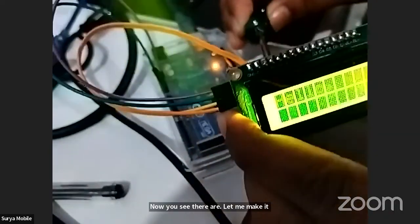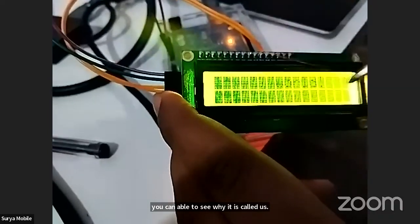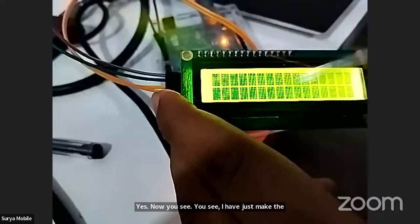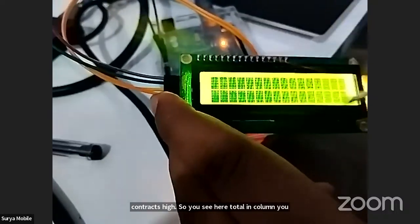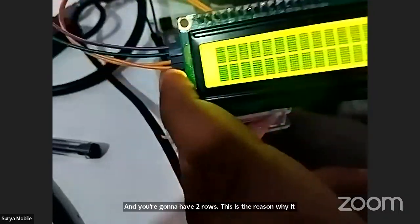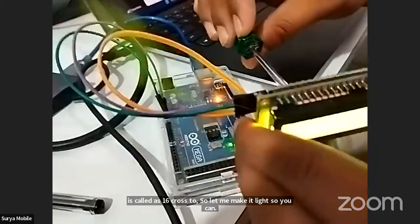Let me make it dark, so you can see why it is called that. Now you see, I have just made the contrast high. In total, you have 16 columns and 2 rows. This is the reason why it is called a 16 cross 2 LCD display. Let me make it light. You can change the contrast using this knob.